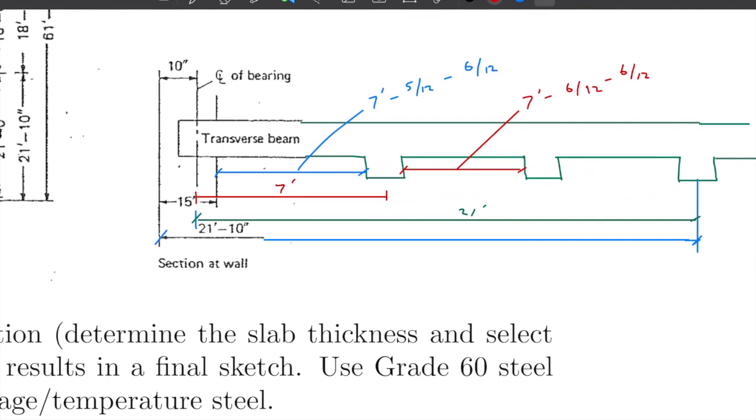And so here is the wall. Try to maybe make that in red here. So this is the wall. Going through that like that, right? And then this beam is coming into the wall. It's embedded into the wall, right? And I would say that it was cast integrally with the wall, right? That's attached in there. It has wall above and below. It's going to restrict some moment in there. So I would say that it was cast integrally with that wall. And so that's what's happening right there.